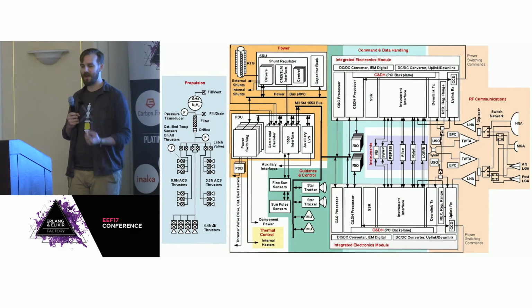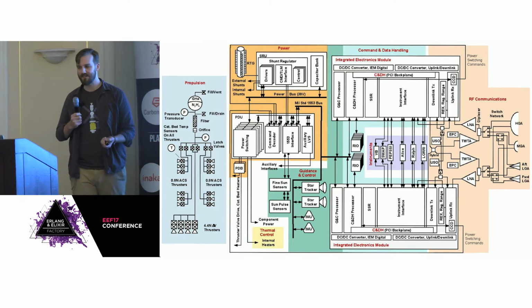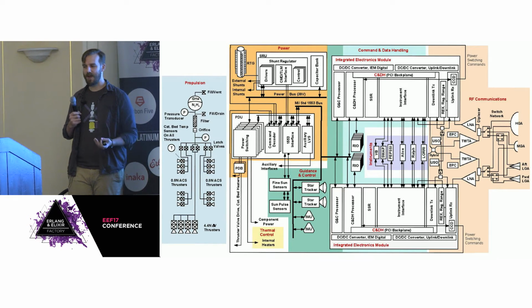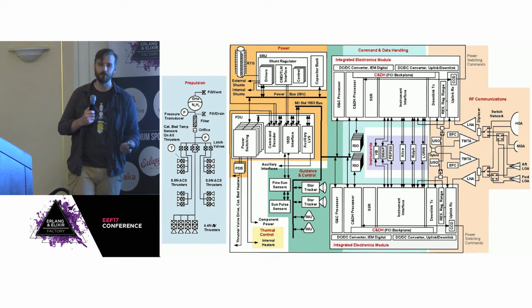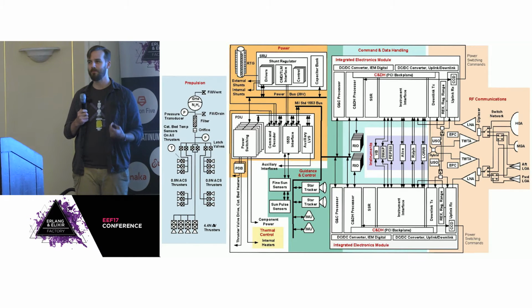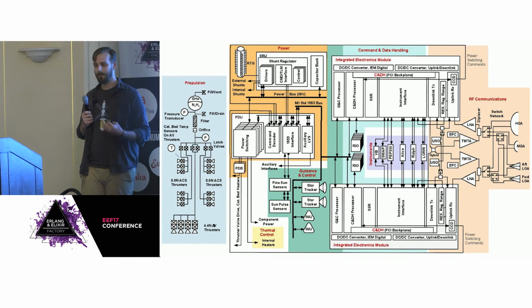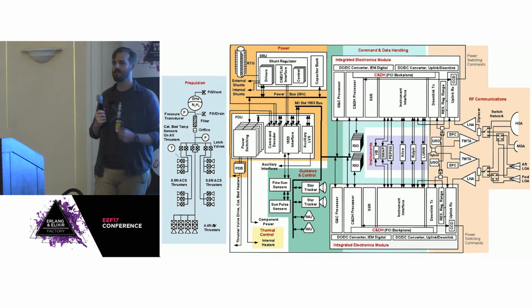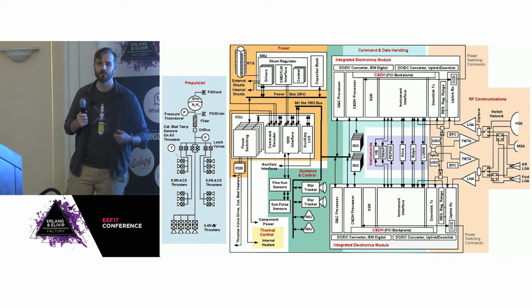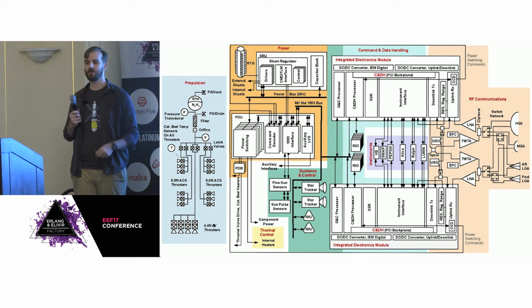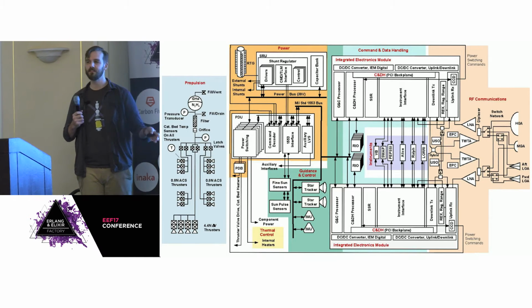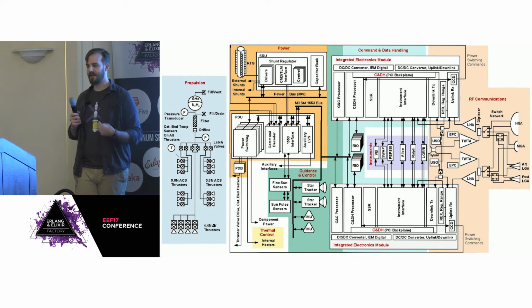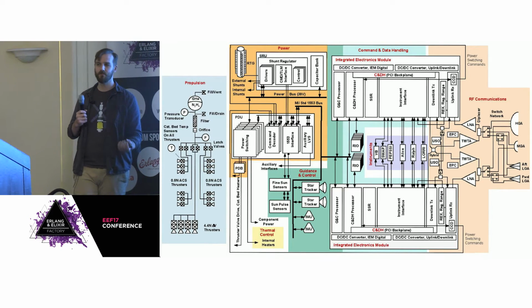So the power constraints on New Horizons are particularly tight. The craft is powered by a single RTG that only gives you 200 watts. New Horizons is unusual in that it has such low power capability. But this means that the software that runs in the New Horizons has to be very power conscious. The software really controls everything. It manages all of the different hardware requirements. Each one of the pieces of hardware sends real-time streams of telemetry over buses, and then the computer system evaluates that, and it either executes a sequence of commands.